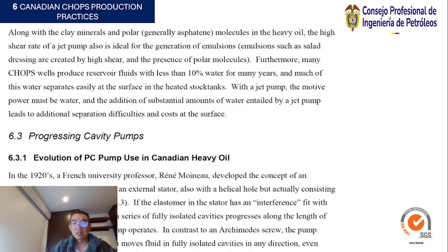If the elastomer in the stator has an interference fit with the smooth surface of the rotor, a series of fully isolated cavities progress along the length of the rotor-stator system.